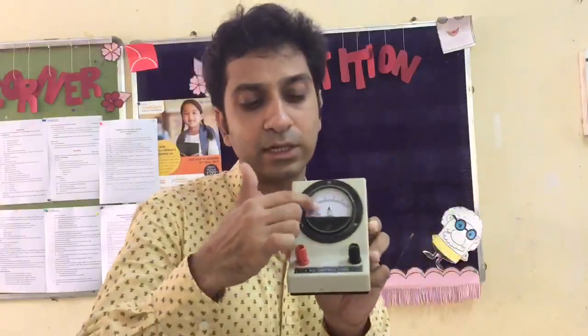It can measure a large amount of current flowing in the circuit. A galvanometer is basically used to measure very weak currents, but an ammeter can be designed in any range, to measure a very weak current or a very strong current. This is called an ammeter, and you can also see the scale is there, readings marked 0 to 5. It means it has a maximum range of 5 amperes. If you are going beyond 5 amperes, you need a different scale ammeter.